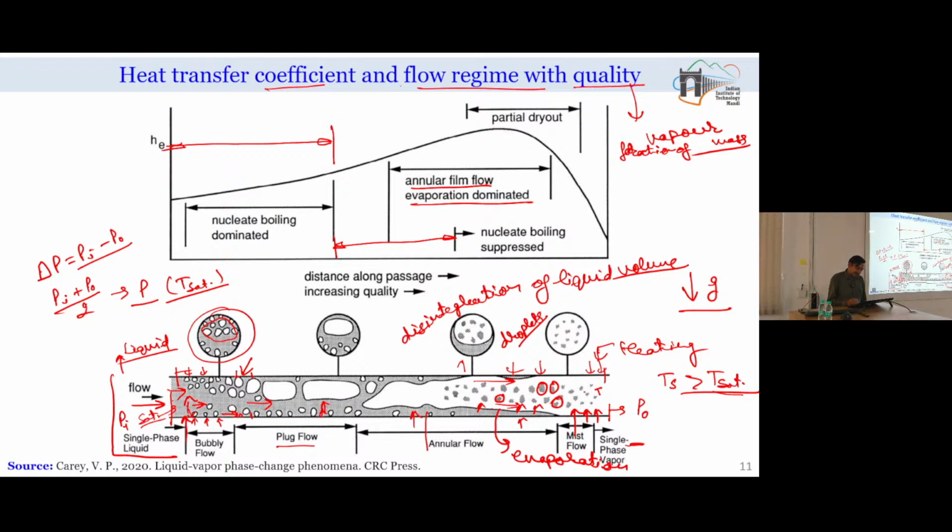Other than that, if temperatures are excessively high, then along with conduction and convection effects, these liquid droplets can also face some radiation effects. So this is the reason you will find that in the nucleate boiling regime our heat transfer coefficient was increasing, but whenever we entered into the film boiling regime, it increased significantly and reached the highest value. After this point, it again started decreasing.